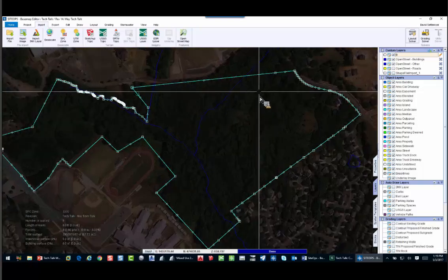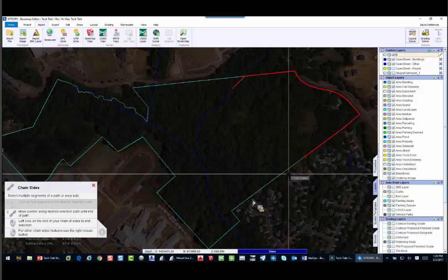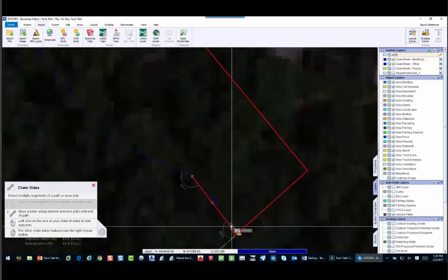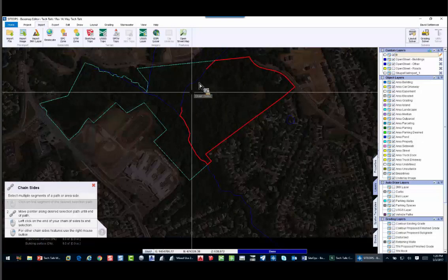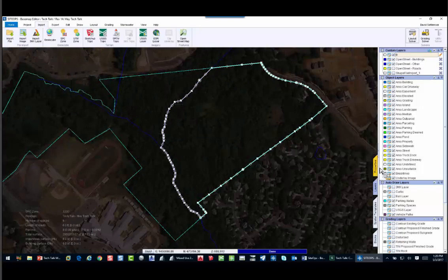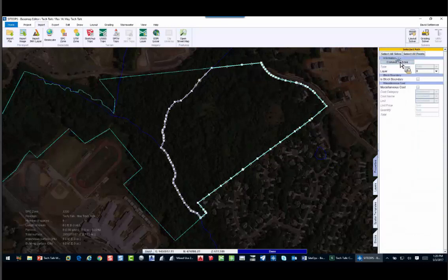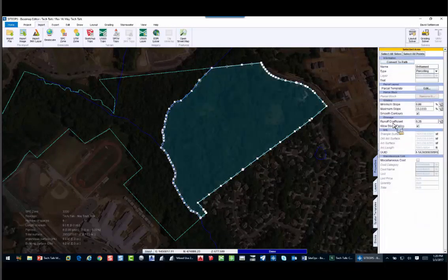So I'm going to go in real quick, and we're going to just identify with that chain tool again. I'm just going to identify an area that I want to start doing some parcel design in. Let's just zoom into the area in the bottom so I can pick up that little line. We'll follow it right back up. And what I've told SiteOps is in this area, I want to design parcels. Now, just like I had to change the boundary, I'm going to do the same thing as we go into this. I'm going to go up to the top, say convert to area. But in this case, instead of saying use as boundary, I'm going to tell it it's a parceling area. And if you noticed, it changed just a little bit. Now, here's one of the really neat things that we do with SiteOps.